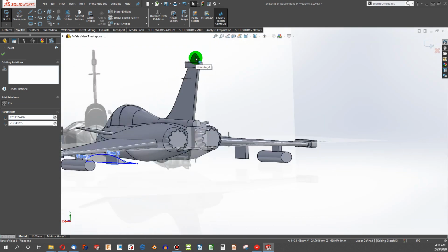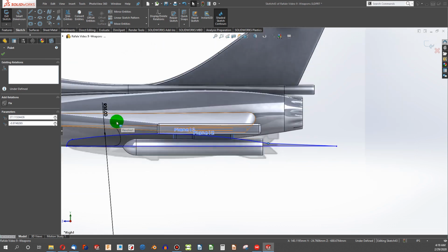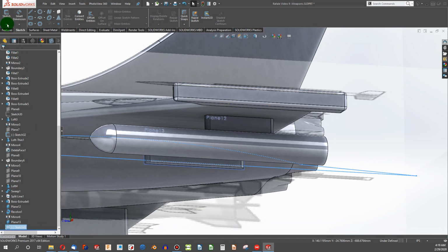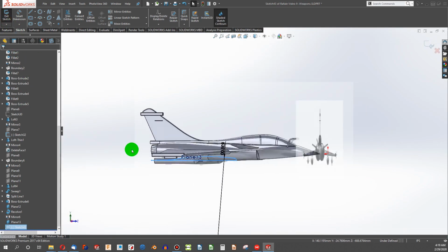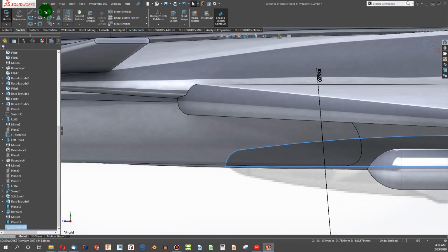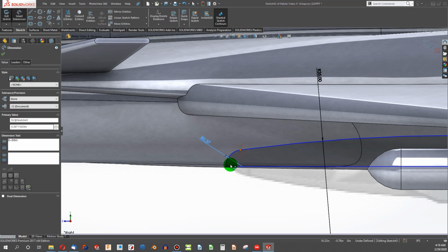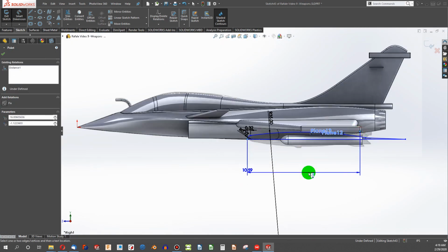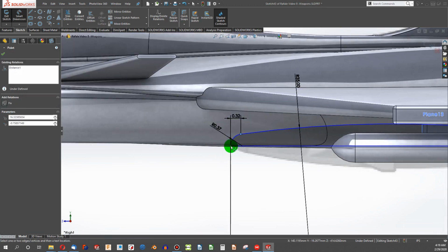Let's get back to our side view here. Again, adding dimensions, mostly, oops, I did not mean to exit that sketch though. We'll add dimensions so that we find that the plane won't be walking around on us. We'll give it radius. Let's say that we care about that distance. We'll again choose some arbitrary points because nothing is actually constrained anyway. We'll give that a height.